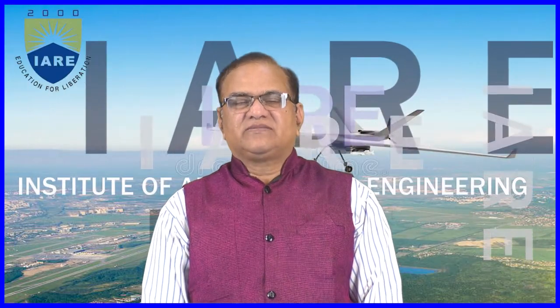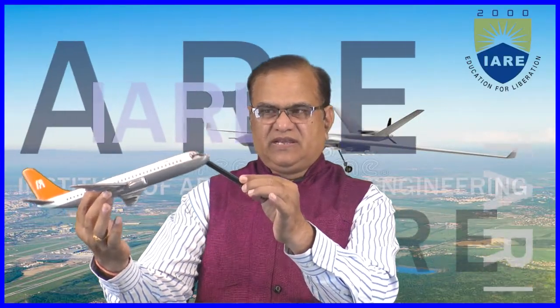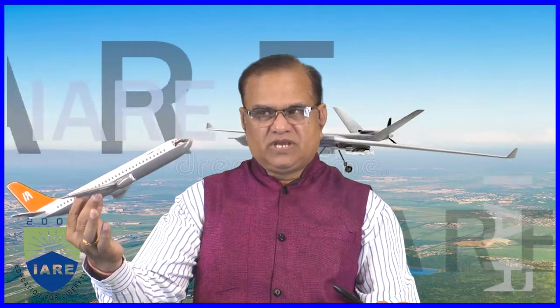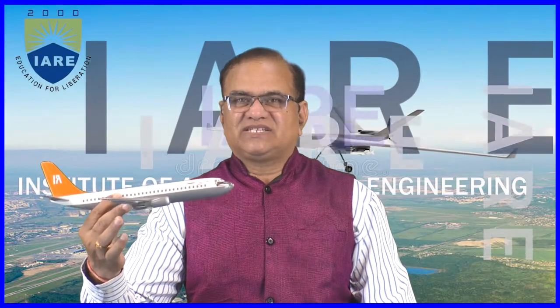When we talk about static stability, take the aircraft flying, and due to some gust coming from this side, its nose has gone up. If you remove this force, whether the tendency is to come to its equilibrium position or not, if it is there, then we can say that the aircraft is statically stable.